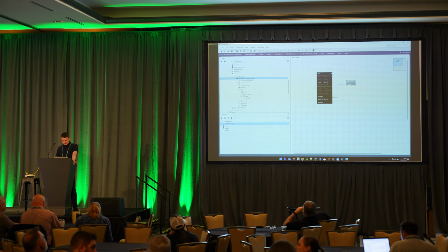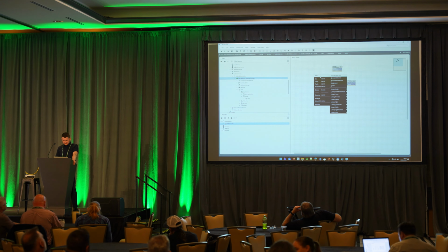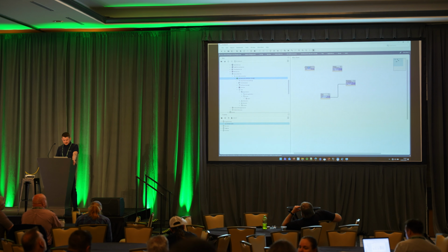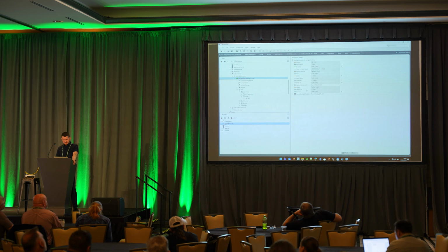So what we can do now is we can do another analog data point, and let's call it set point. And build some logic around it as well. So let's say that we want to create some math here. So we want to have a schedule, analog schedule for our point. And we can set the schedule. So this schedule is also natively being shared over BACnet, so you can already discover it. But we want to have some default value here when the system is not occupied. So let's set it to 68.